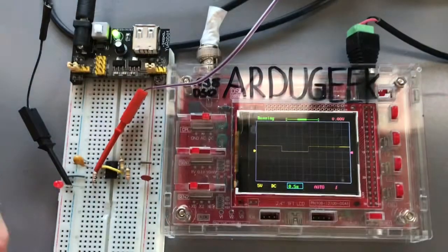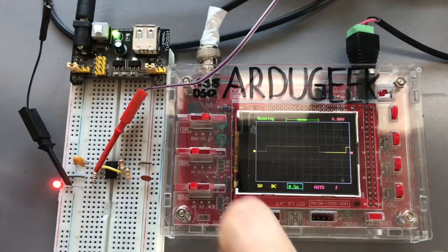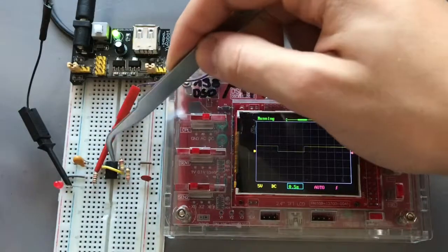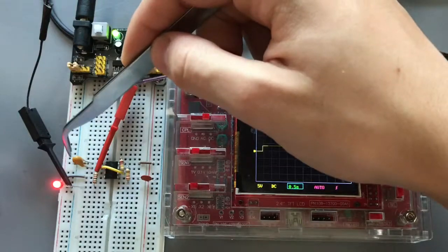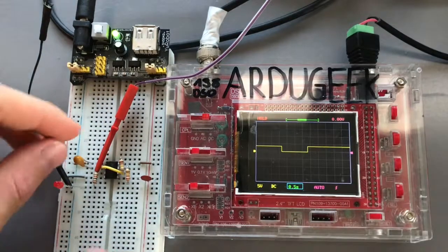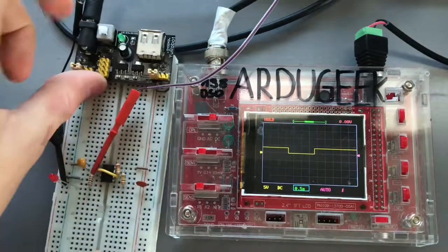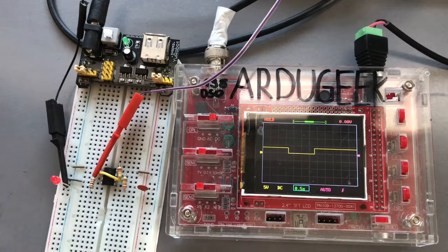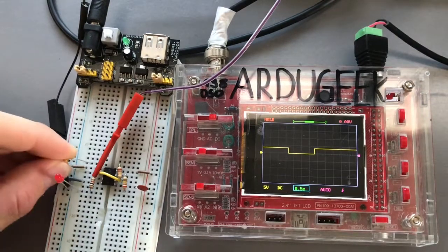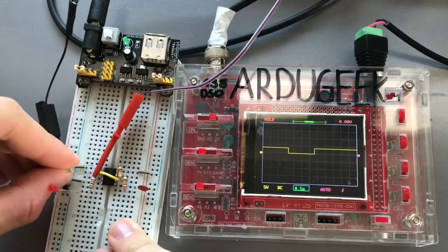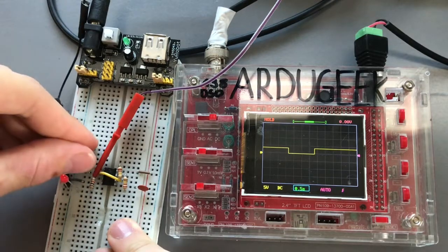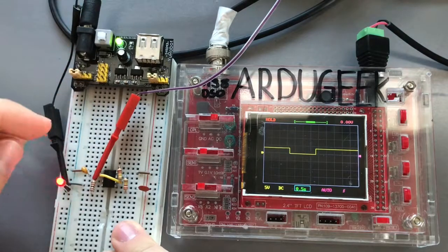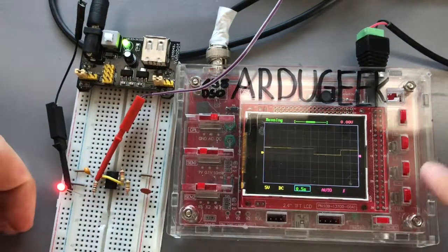And the oscillation of this astable multivibrator is mainly dependent on those resistor values, as I said before, and on the capacitor. If now I turn off the power supply and replace the 10 microfarad with 1 microfarad, like that, put it in here, it will oscillate faster. As you can see, it oscillates faster now.